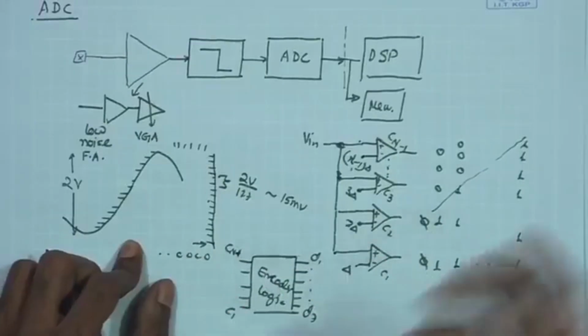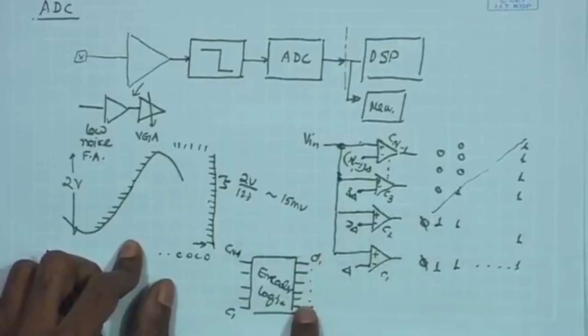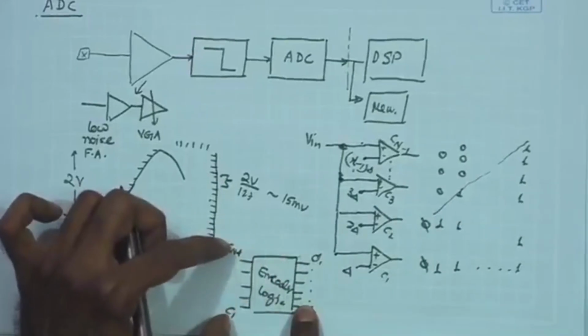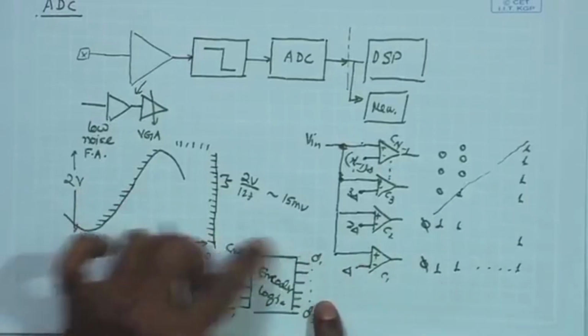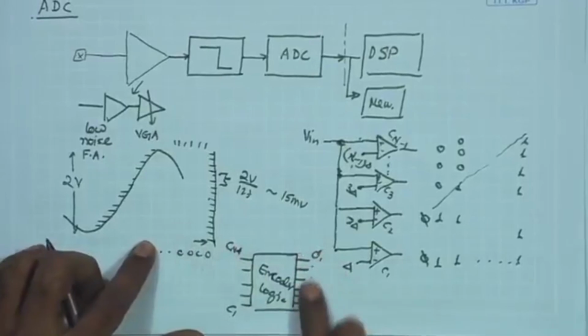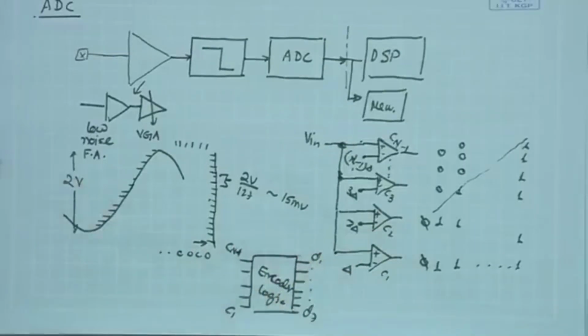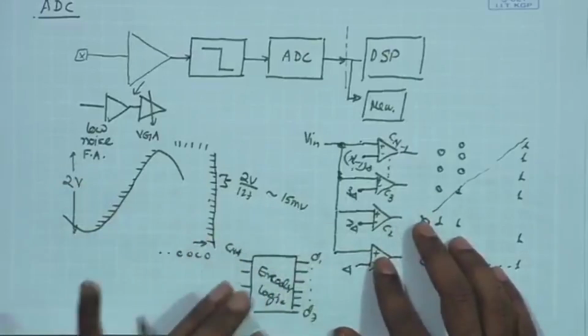So, basically we can write a truth table for each of these 7 outputs as a function of these n minus 1 inputs, and then simplify the logic function and arrive at the logic implementation of the individual outputs. That can be done using a K-map, and a computer can solve it because you have such a large dimension of inputs.